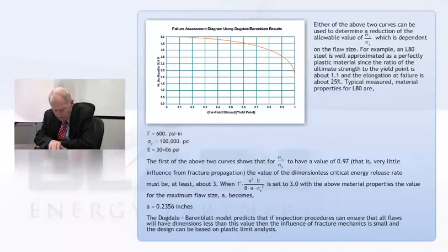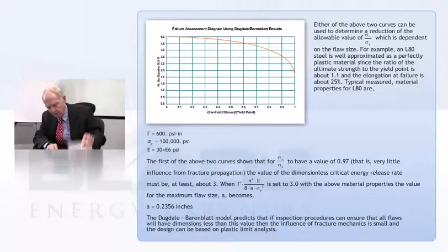Okay, yeah, I took a value of this energy release rate, which is really taken off of the preceding curve on the preceding slide, and I just pulled out a number of 3, and that gave me a far field stress of about 0.97 of the yield stress.